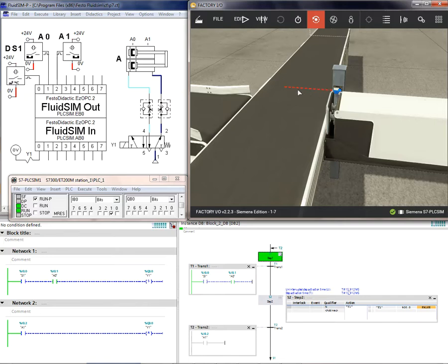As you can see, the production lines, and in the programming language, S1 as diffuse sensor 1 works as input I0.0. As you can see, S1 is I0.0, and this is the same, S1 is I0.0. Okay, let's see.